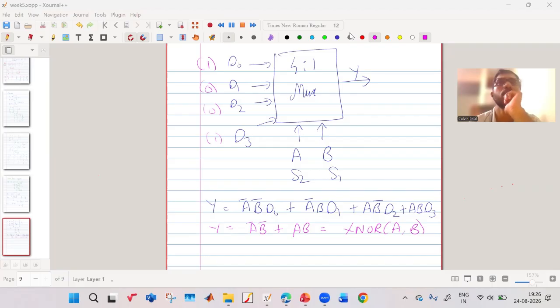Yes, you can do that in digital. You could also try generating the FFT, fast Fourier transform of your signal, and maybe checking the RMS value and those things. That is something you can do.